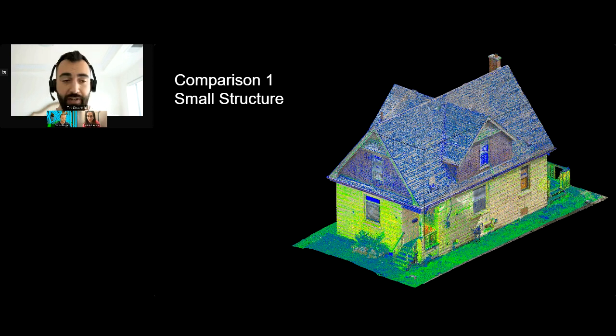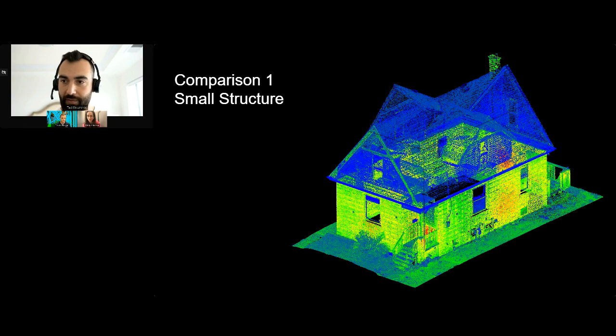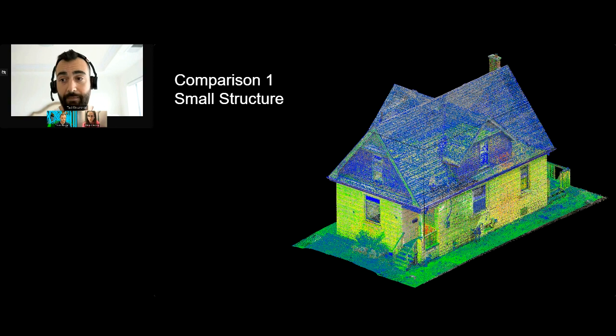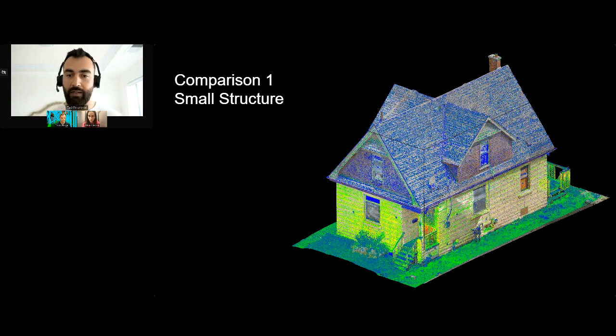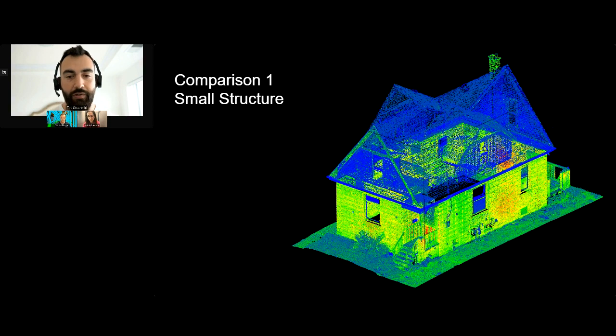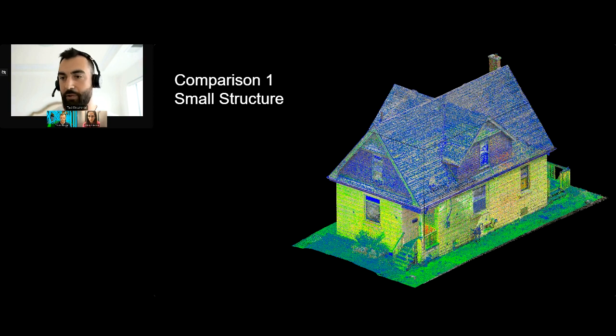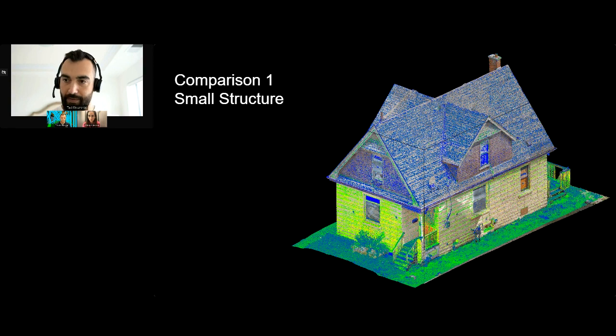Laser scanning can't show you color, but it can show you how reflective the surface was that the pulse of light or phase of light bounced off from, and that replicates color quite well. So you can make out certain details. You can't really use it for inspection, like bridge inspections or structural inspections, but there is some detail there that allows you to conceptualize what you're looking at and see the difference in materials as well.